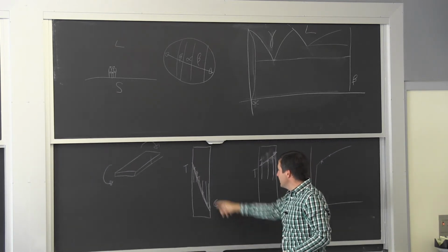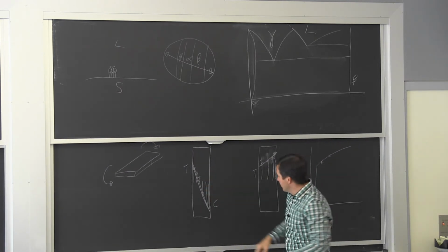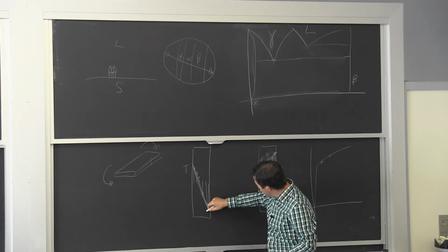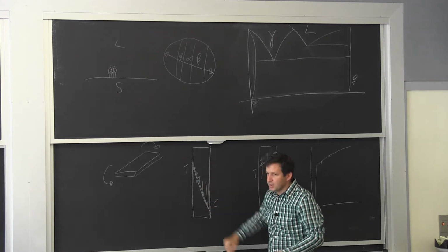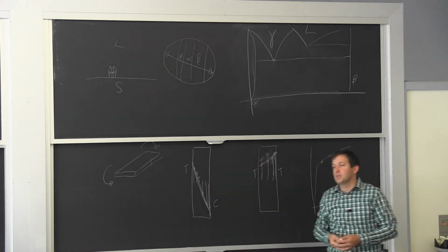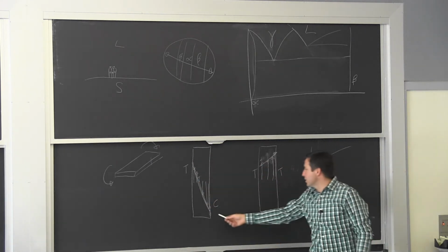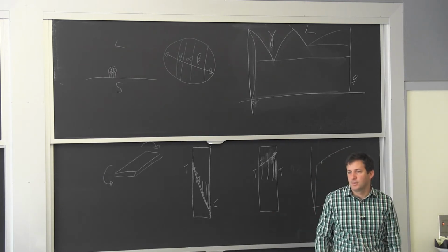When you have this here, it's not exactly linear because you have the deformation taking place. You have more deformation here, and you have more deformation there. So there will be built-in residual stresses in this configuration and very little in that one.